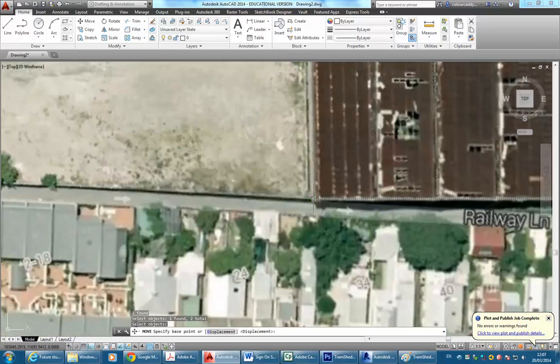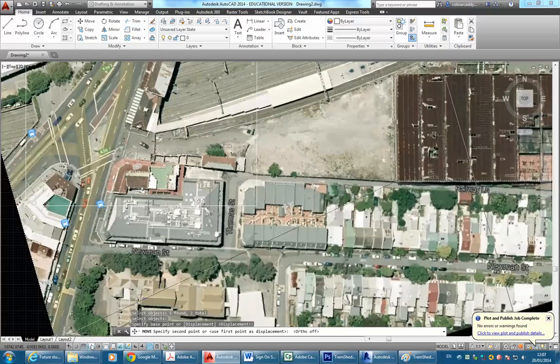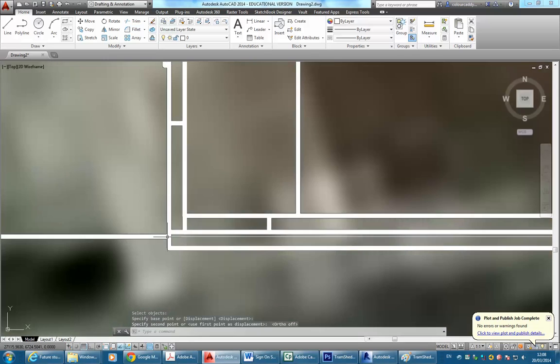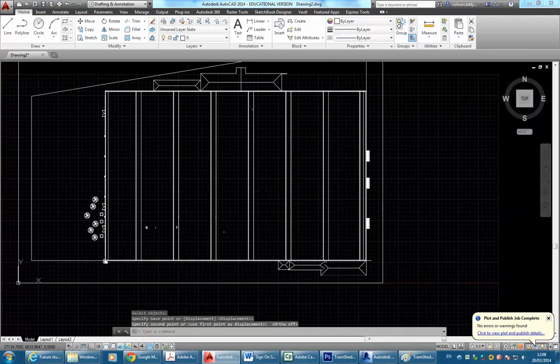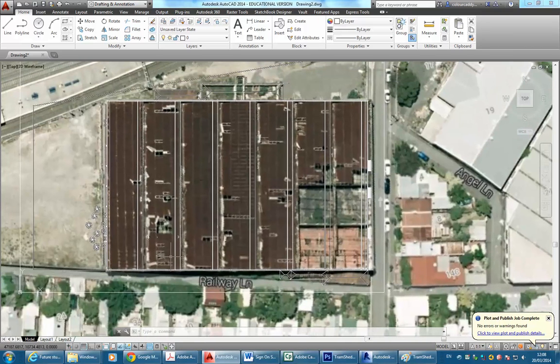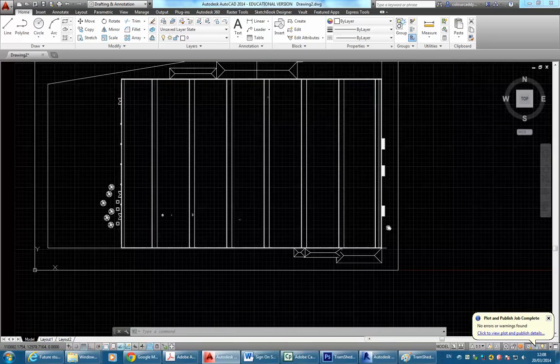And then I'll use the corner of the building as my base point and snap that with Auto off to the corner of the building in my PDF, which is actually going to be probably this corner. So you can see there, not bad. It could probably be adjusted a little bit, but that's when you can fine-tune things like your scaling. I can see there, yeah, I did get the size right, but there's a bit of inconsistency there, so I might just fine-tune that slightly.